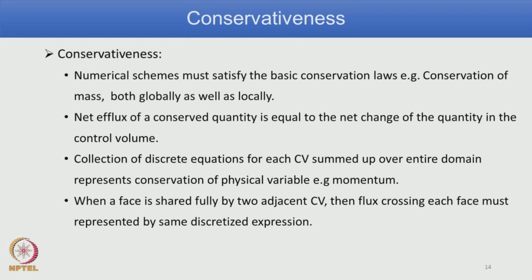So, when a face or control surface is shared fully by two adjacent control volumes, then the flux leaving one face must be exactly equal to the flux entering the adjacent control volume. If you write it in a discretized way, in one it will be positive, in another it will be negative, balancing each other.